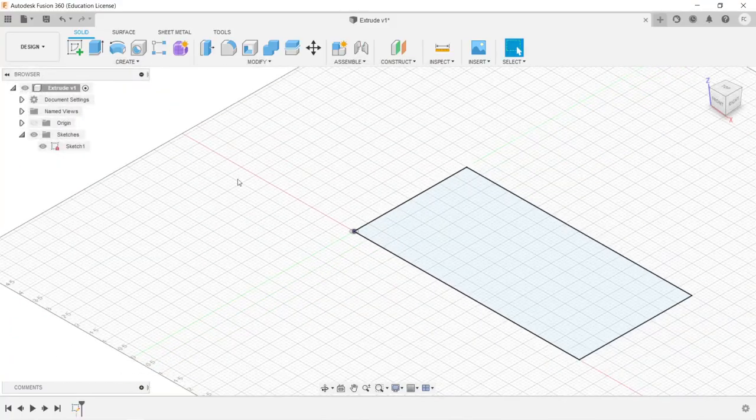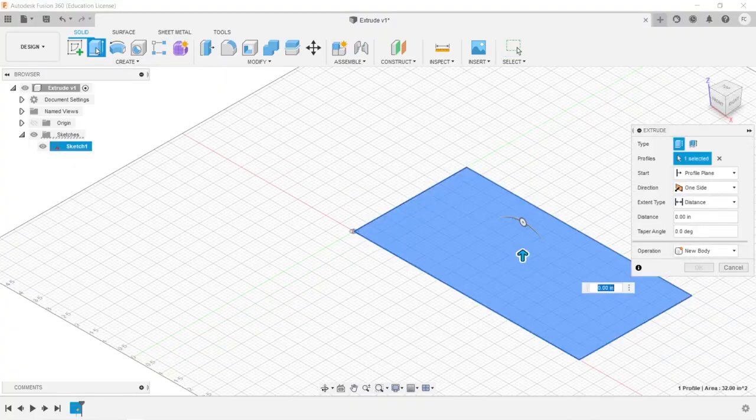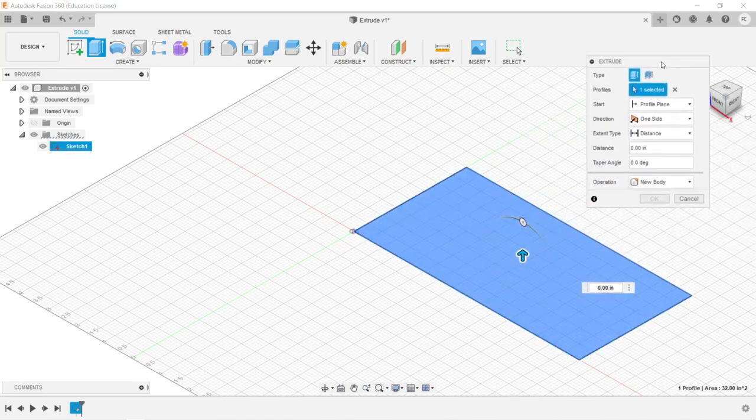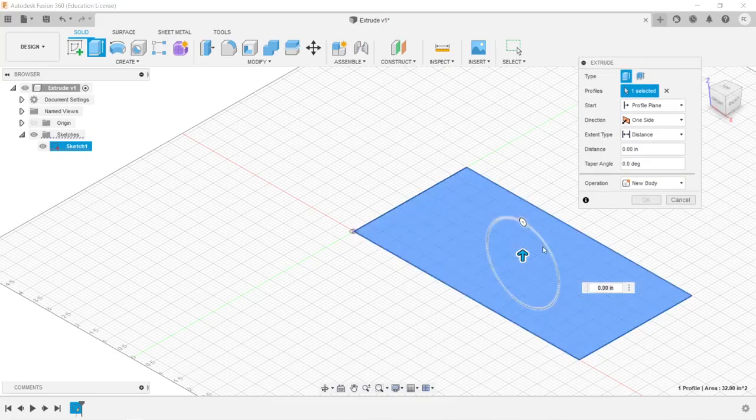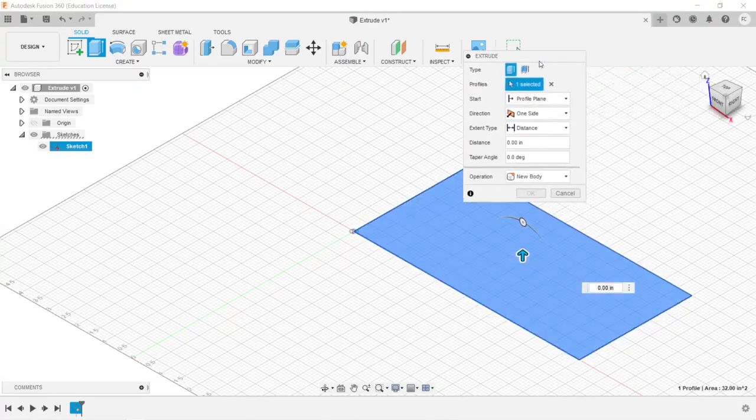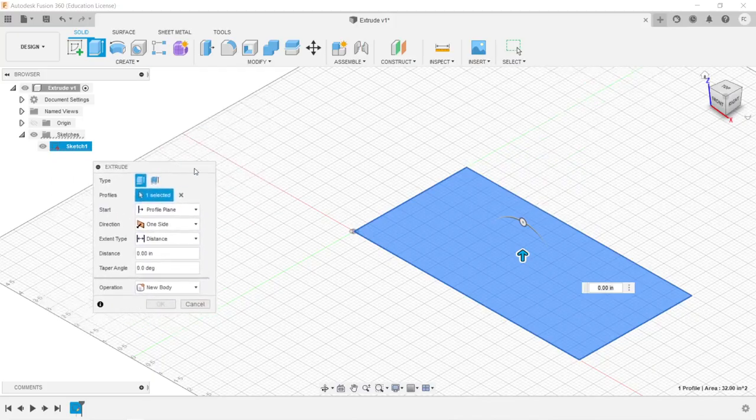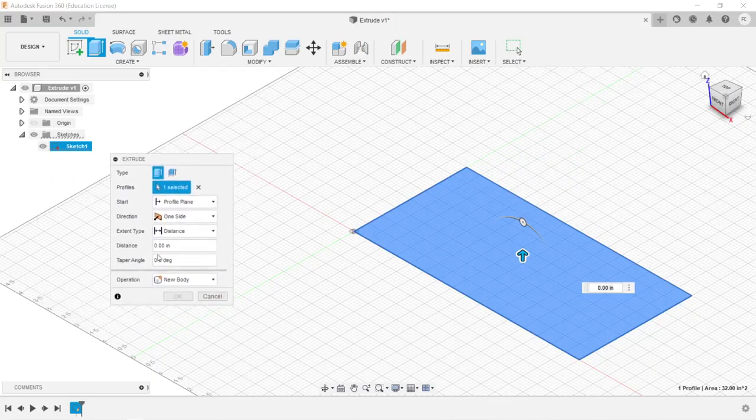All right. So now what we're going to do is go ahead and extrude. We're going to click on the extrude tool, and I can pull this up. I can rotate it. Because mice are kind of glitchy, especially if you're in a browser with an internet connection, it's problematic. So you can do everything that you can do by dragging these, what they call heads-up controls, in this very nice, very dependable dialog box. So let's do that.